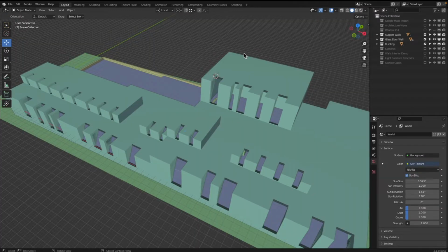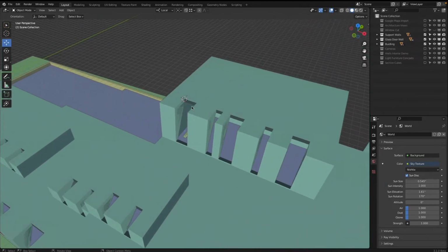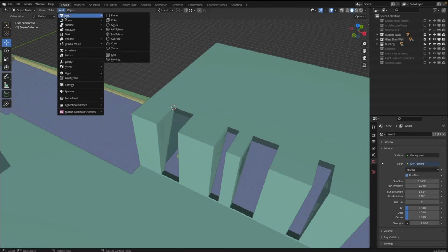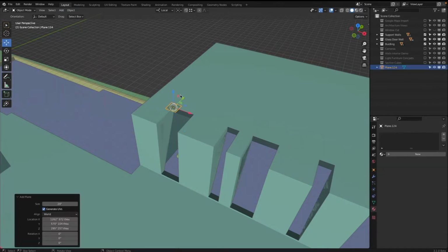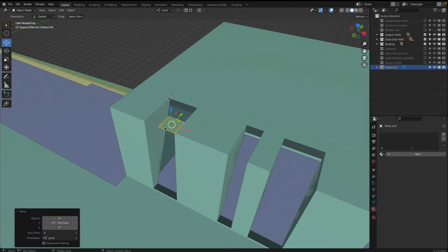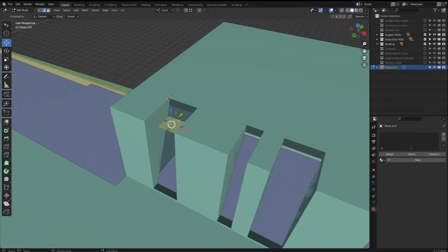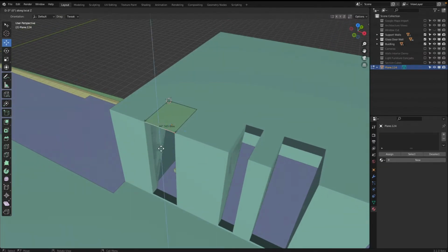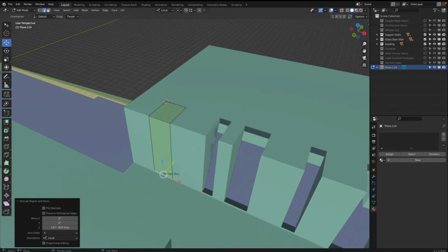So let's create the geometry for all these window openings. I have the 3D cursor positioned. Point snapping, move command is on. Add new mesh plane. Then I can move, hold Control and snap. Hold, snap. Going to edit mode, edge select, bring this over, hold Control. You see I'm just moving and dragging with E and Z, so extrude and Z constraint, hold Control, click, there we are.